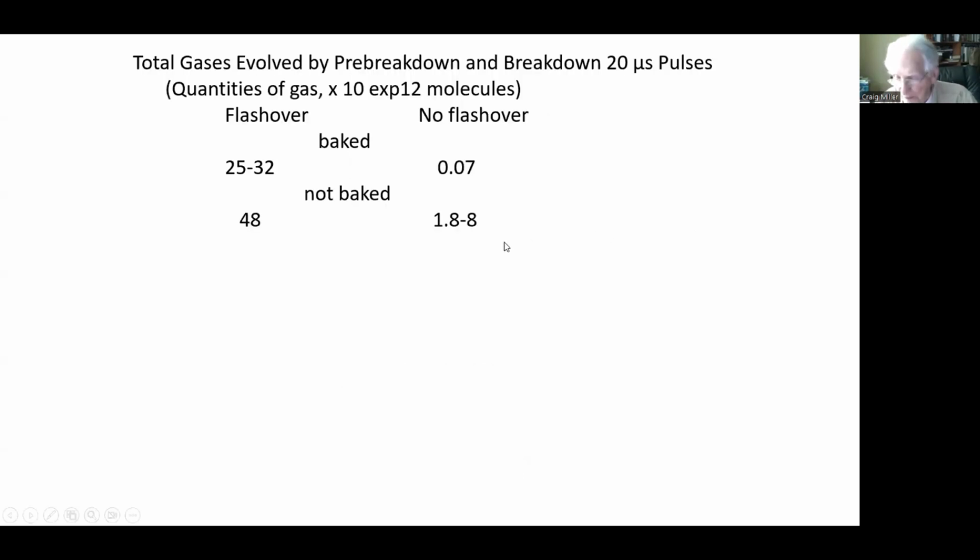So now, as we discussed earlier, the final flashover in an insulator occurs in desorbed surface gas. So we did an experiment years ago. This happens to be one of the inverted alumina insulators, which I did a lot of work with. We did two tests. One is we assembled the alumina insulators, tested them, flashed them over, then baked them out and retested them. The second series, we baked them out at the start, then exposed them to the atmosphere and retested.